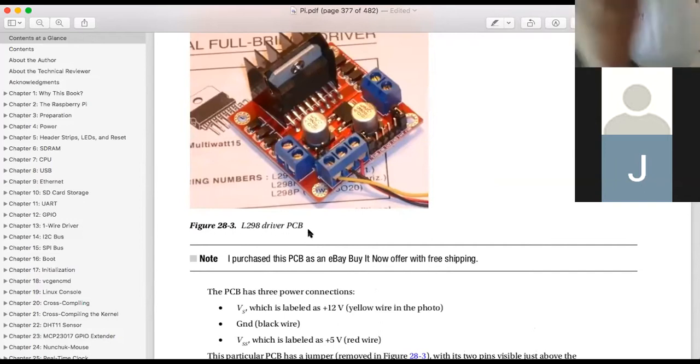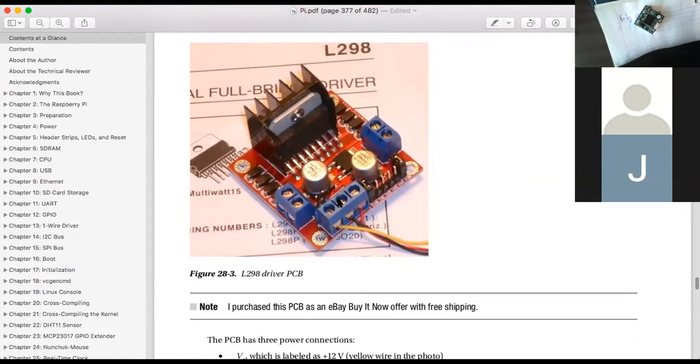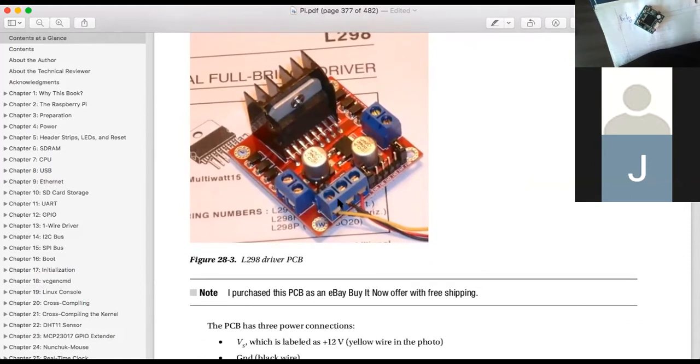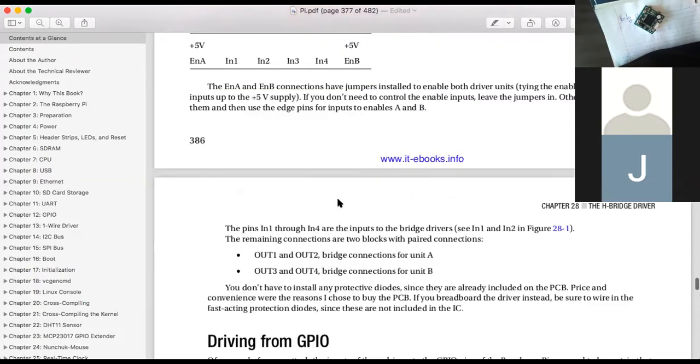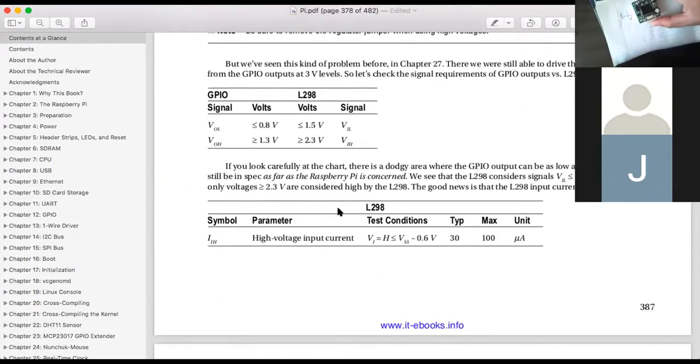And those H drives, of course, you can always build one yourself, no problem. But generally, the author has an example here. You buy the H drive. It's inexpensive, actually cheaper to buy a pre-made H drive than to make it yourself. So the author provides one example over here, and on my camera I have another example. That's the H drive right in the middle. This will talk to a computer on one side. Those are the computer connecting wires, and then the power and the motor are connected. Those are the power connections and the motor connections.